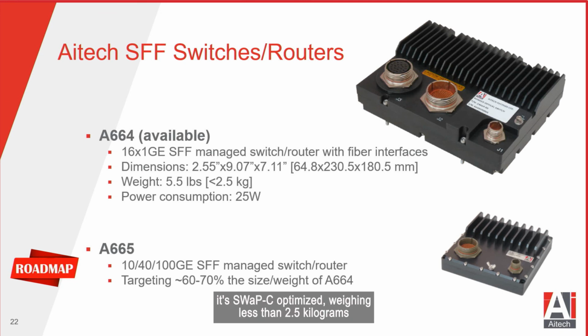It's SWaP-C optimized, weighing less than 2.5 kilograms, with power consumption limited to 25 watts. And the next generation switch in this series, the A665, is currently under development and will feature 10 gigabit Ethernet, 40 gigabit Ethernet, and even one or more 100 gigabit Ethernet optical interfaces within a much smaller enclosure.